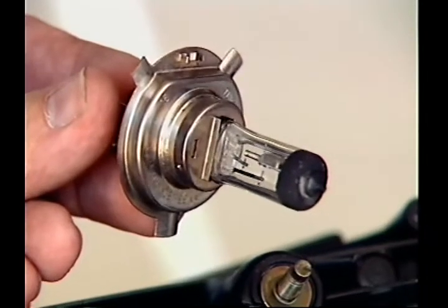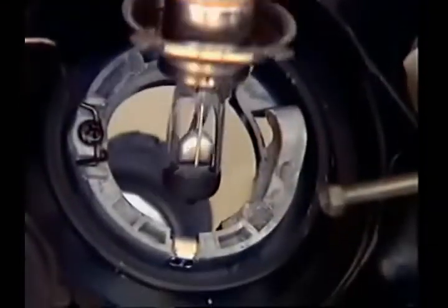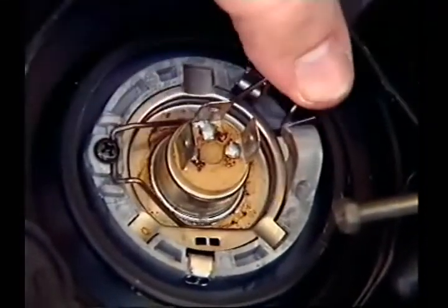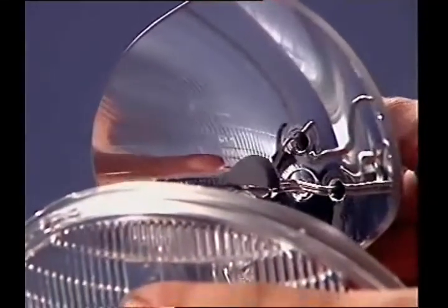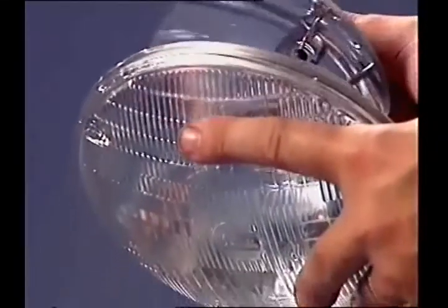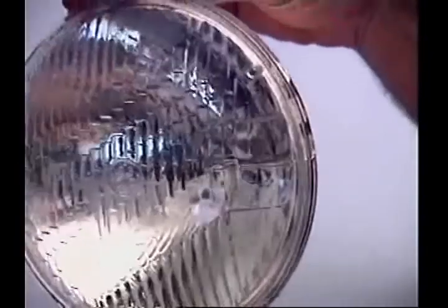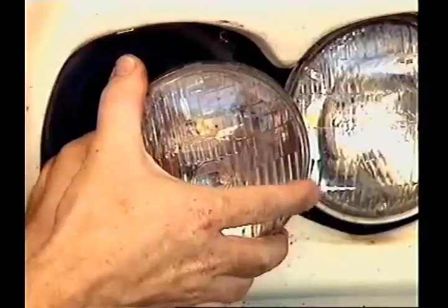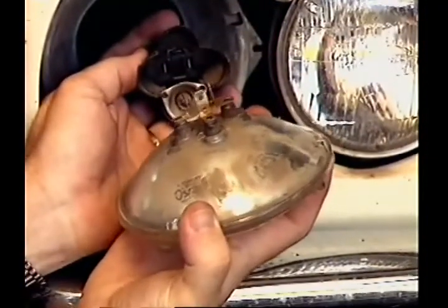A semi-sealed beam headlight uses a replaceable bulb with a pre-focus collar. The collar locates the bulb in the headlight and also controls the correct positioning of the filaments. A sealed beam headlight has a highly polished aluminized glass reflector, which is then fused to the optically designed lens. This forms a completely sealed unit which has the filaments accurately positioned in relation to the reflector. When a filament fails in a sealed beam light, the whole unit must be replaced.